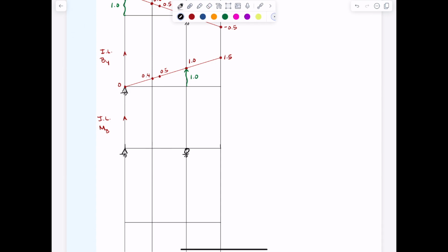So we're going to put this hinge in, but then the rest of the structure has to remain solid and straight, because the influence lines for determinant structures are always straight. So I come into this hinge and I'm going to apply this unit rotation. That unit rotation is going to be 1, and it needs to be 1 total, not necessarily 1 on each side. So I scratched that out, because it's going to be 1 total, between theta left and theta right.